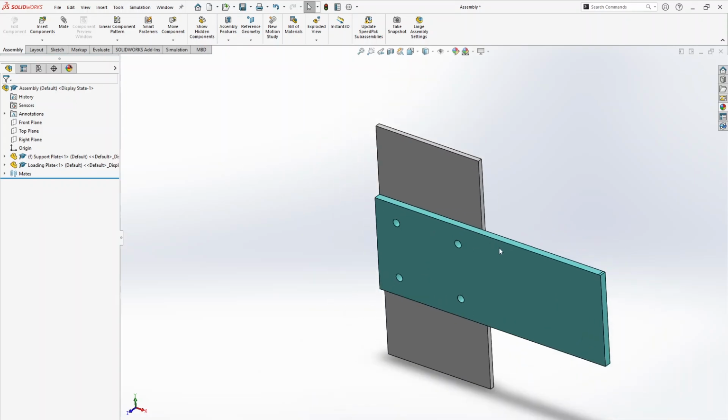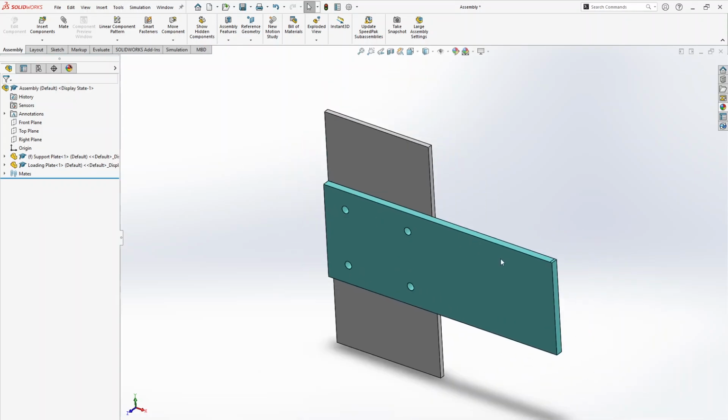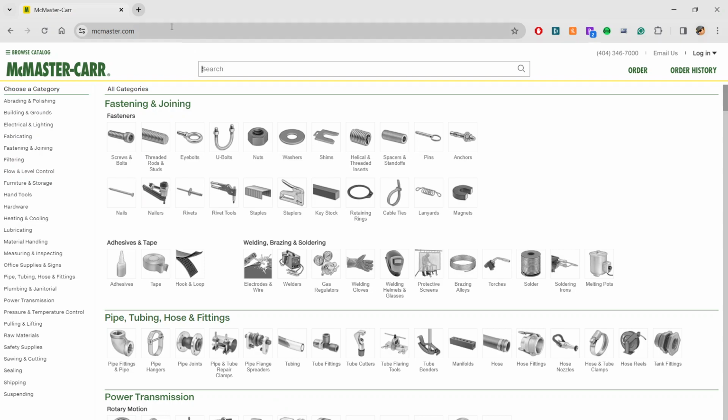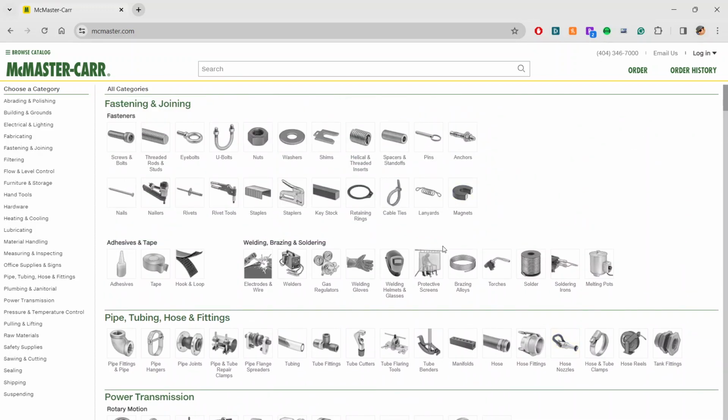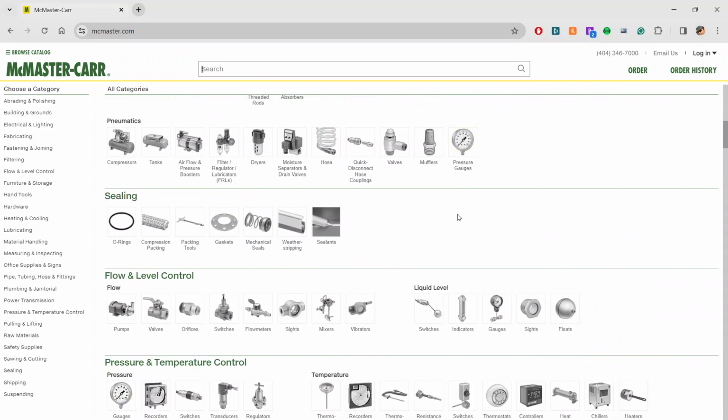Before doing that, I would like to discuss a database of the fasteners, how in industry those fasteners are defined. We discussed the fasteners in the previous class. There is a very good website that I wanted to use in conjunction with this simulation, and not simply accept the default values that SolidWorks suggests. The site is McMaster.com, the McMaster-Carr, and it has a very large, very accurate database of a lot of fasteners and small parts.